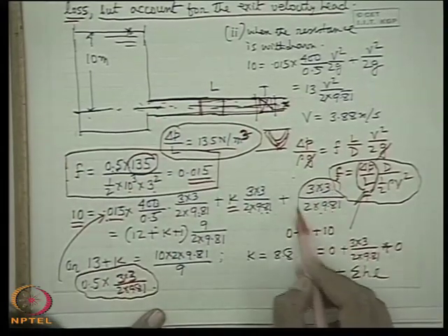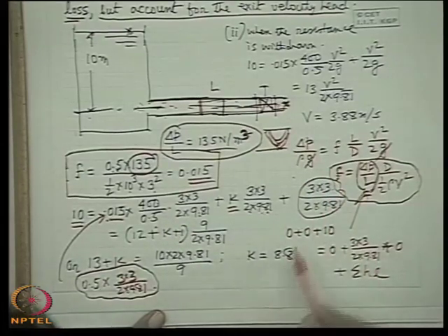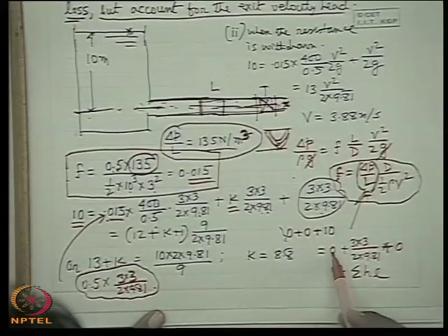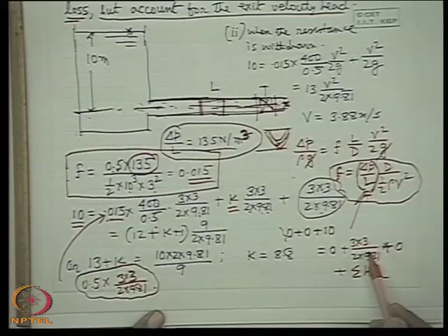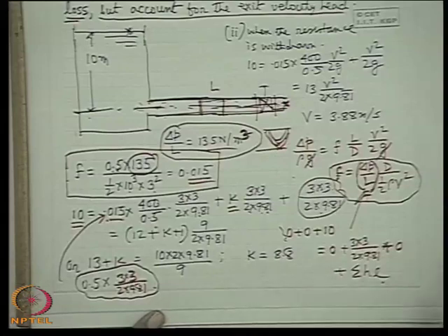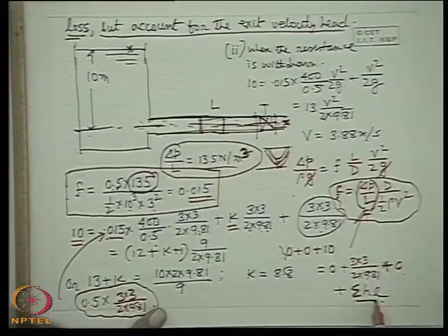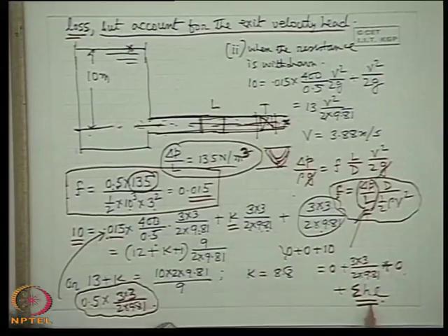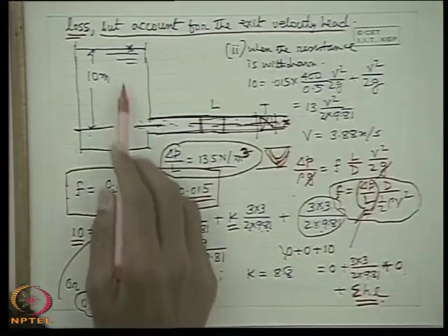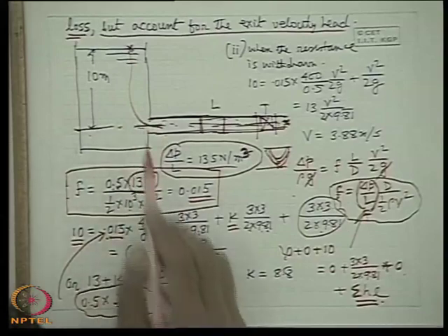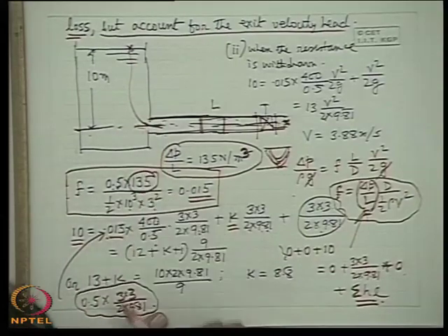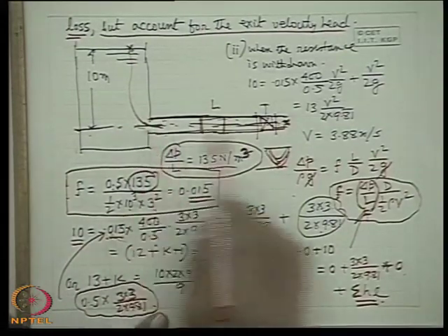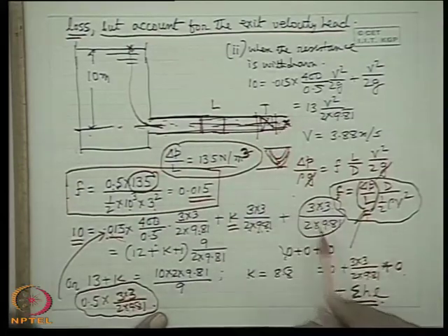In the modified Bernoulli's equation, we write the pressure head, velocity head, and datum head, which is the conventional sequence, plus the losses up to the downstream section if the flow is viscous. That is a modified form of Bernoulli's equation considering the viscosity of the fluid. But in the conventional friction equation, people go on writing as if following the path: first the fluid encounters the entry loss, then the friction loss, then this loss, plus it has a velocity head.